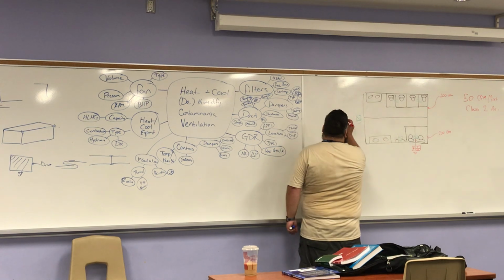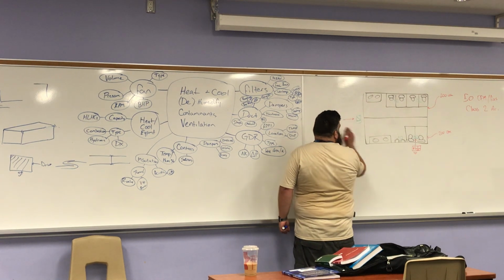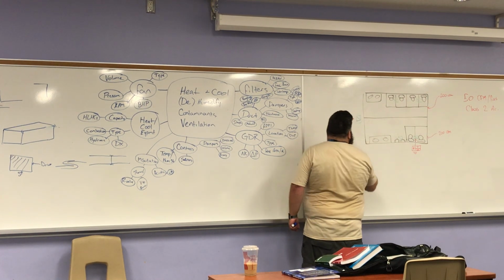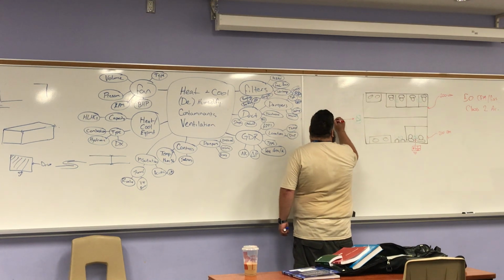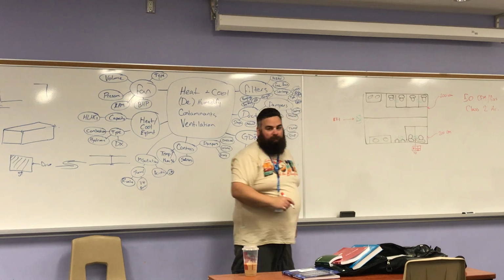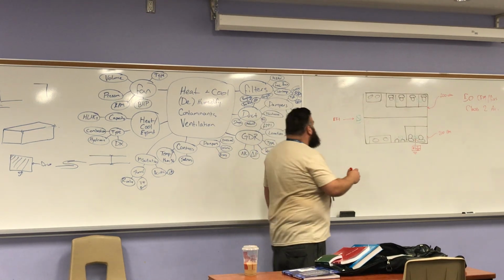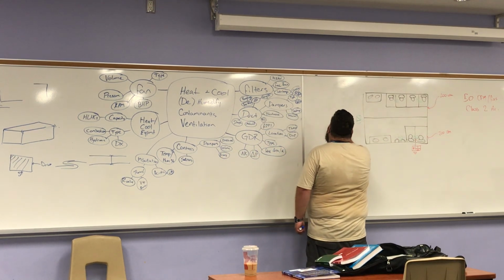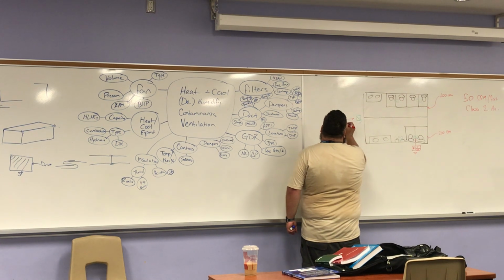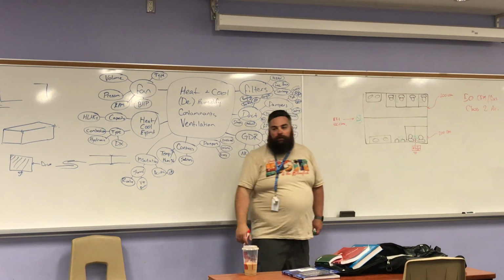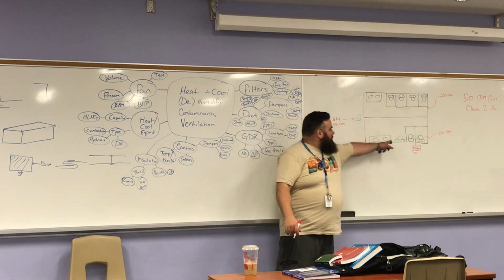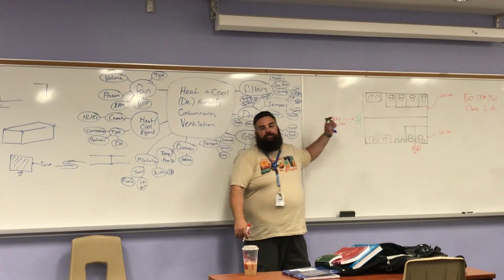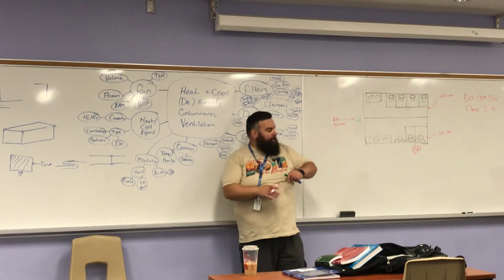200. Yeah, 200 ones. So each grill was 100 CFM. So that's 400. It's gotta be 400 CFM, right? Conservation of mass. Everything must be accounted for. All the air that gets drawn in there must discharge from the fan. Okay?